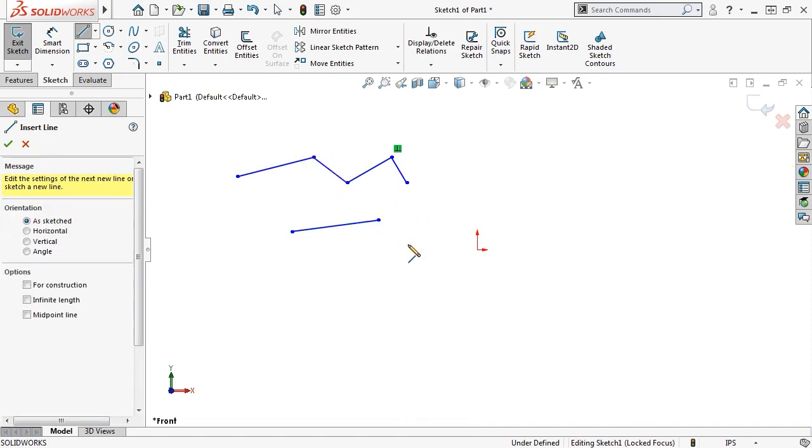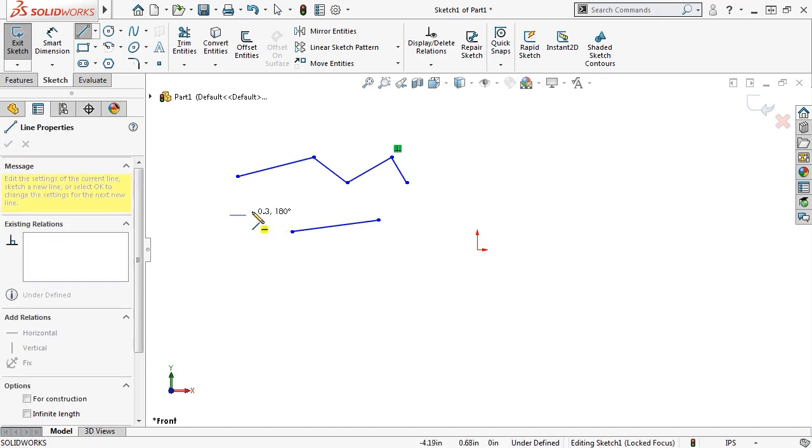There is a slight variation to this method of creating geometry that many users prefer. Instead of clicking to begin a line segment, then moving the cursor and clicking again to add a point, you have the option of click dragging. I'll click and keep the mouse button pressed. Then I'll drag to the location where I want the line segment to end and release the button. The difference, as you can see, is that no chain of lines is created, just one segment. For those that don't want to worry about ending chains, either by right-clicking or double-clicking, this might be a better method. Other sketch tools work very much like the line tool.